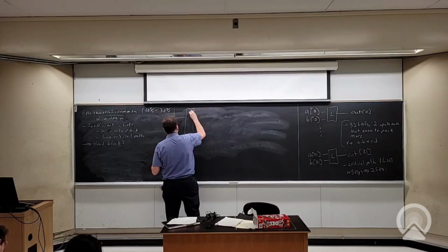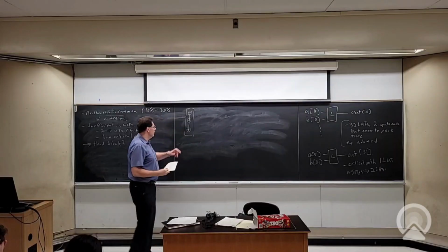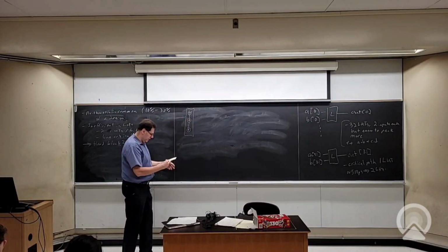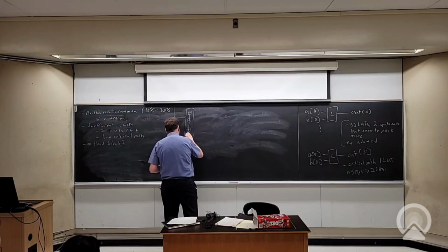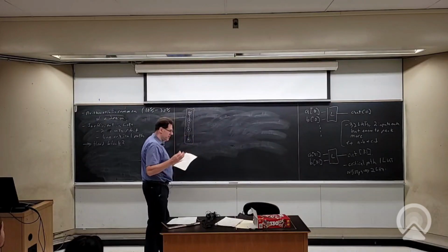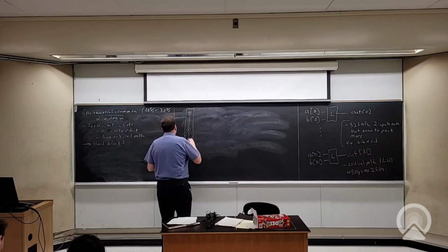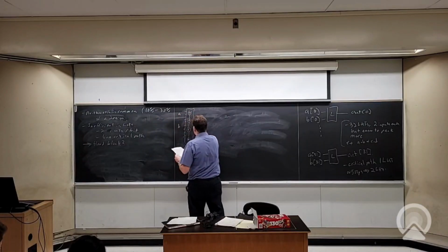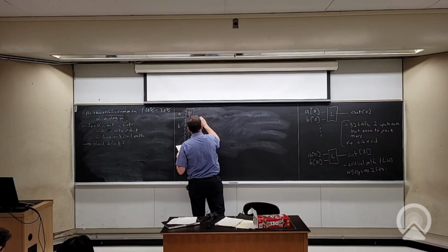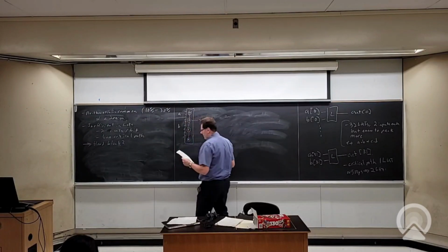Okay, so I've got a full adder, a full adder, a full adder. These carries are my problem. So the carries are now just wires going between these full adders. I'll probably make it more than 3 bits. Yeah, let's make it a bit more than that. Probably I'd make this a whole bunch of bits, maybe 16 bits or something like that. I've got a bunch of inputs here. I bring in A and B. Now they both have many bits. I bring out my sum. It also has many bits.